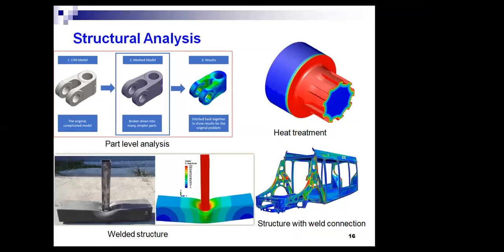So the degradation of the material, and the quantity up to which the material strength is degraded, has to be evaluated prior to applying any manufacturing process or developing any designs through such manufacturing processes. So a virtual platform will help us to understand such deformation behavior, and the residual stress present in the product after welding can be analyzed in a virtual environment prior to developing a physical prototype.